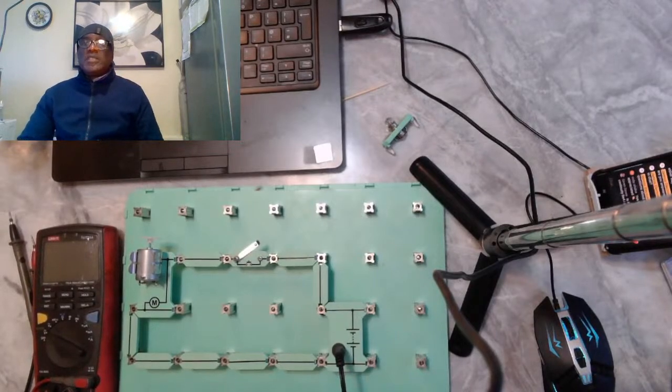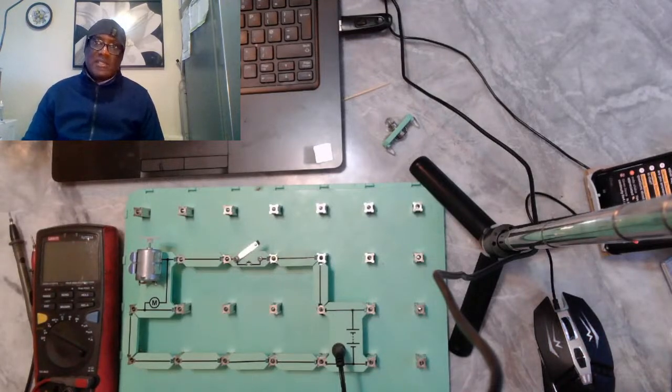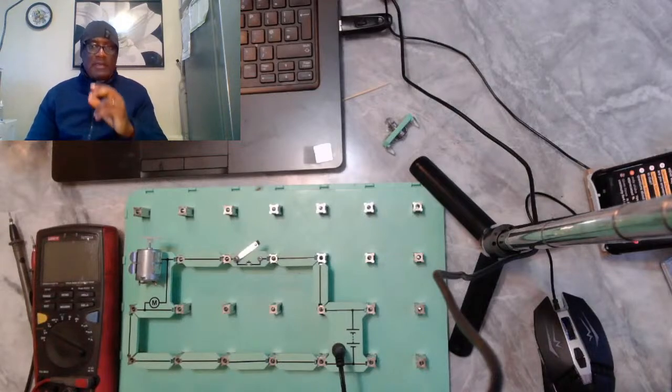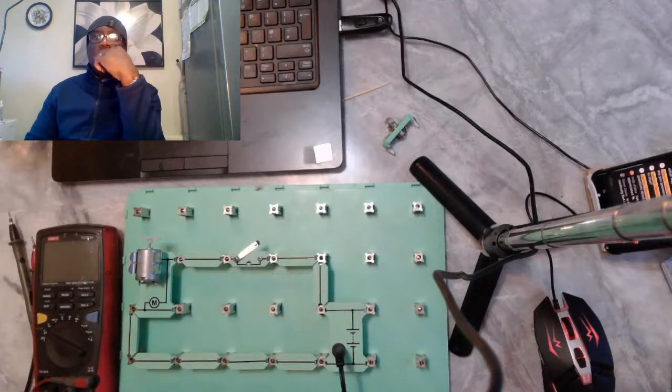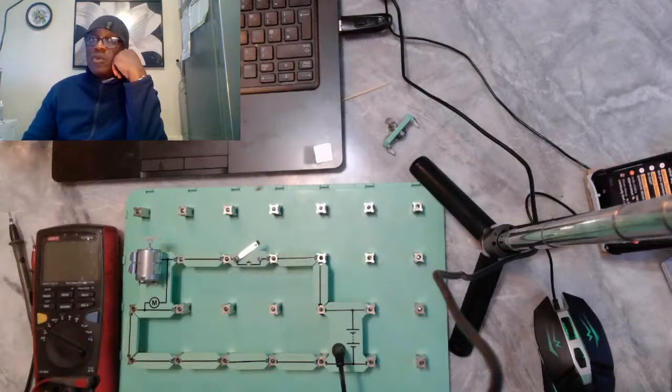I've seen continuity really cause problems in my life as a technician, in the sense that you will find that in a wire, maybe only one strand is left connecting the whole wire. If you check continuity, it will buzz.